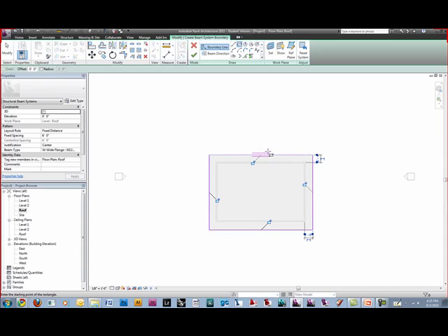And you'll see these double lines here. There's one here and there's one here. That tells you what direction your beam is going. Now let's say you wanted the beam to go this way versus this way. You could easily go up here to your beam direction and then select the line you wanted to follow. So say you want to follow that line. They used to not do this in the other program. In 2010 and 2009, you couldn't select the beam direction. It just had to be the first one you drew was the direction, which was really strange, and nobody really caught on to that.